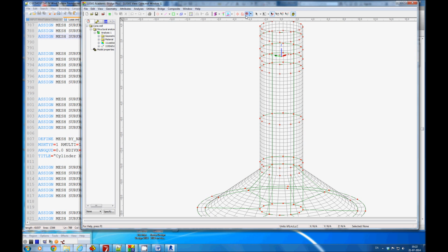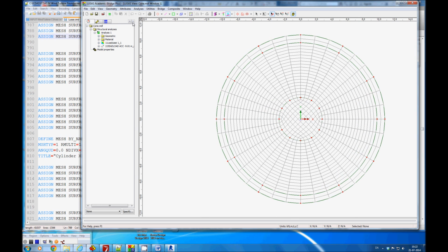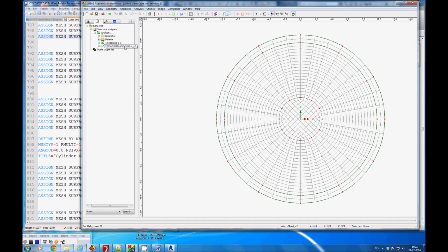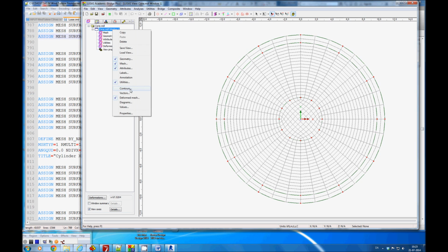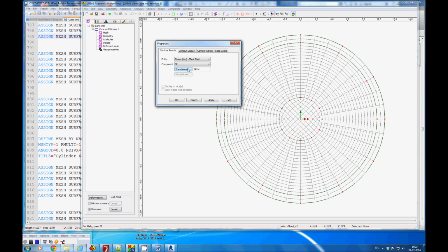Then we look at the top view and do the same again. I go to activate load case, activate dead load, set active. Turn on the icon for load. And then go to the layers tab, right mouse click on the model, open the contour. And we would like to see the same stress top in X direction.